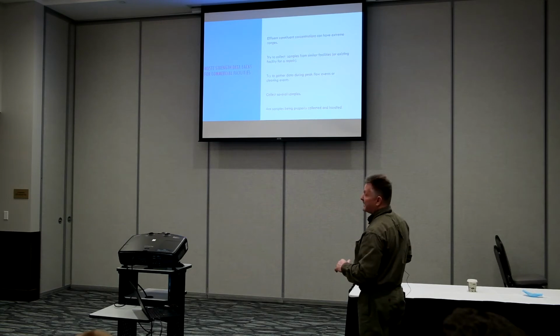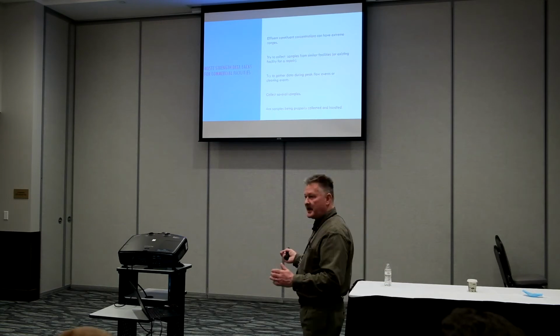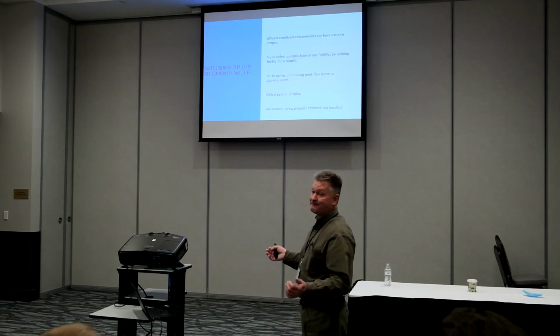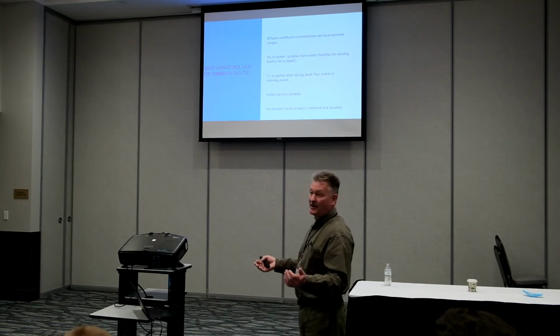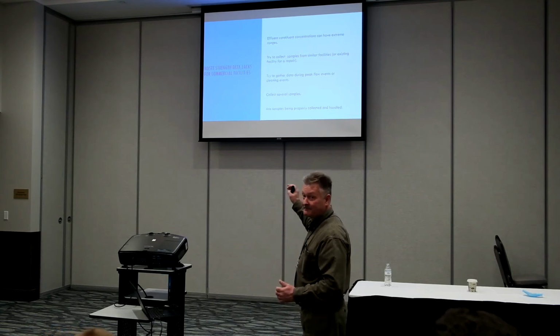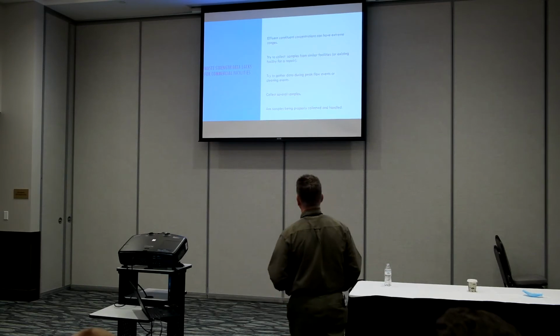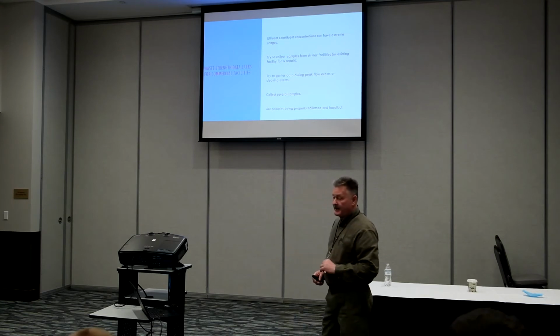We also want to get those samples during a peak period. If you were to sample a restaurant's fats, oils, and greases on a Monday night, when they really haven't seen any flow all day, you're going to get totally different results than on a Saturday night. Then we want to collect a lot of samples.